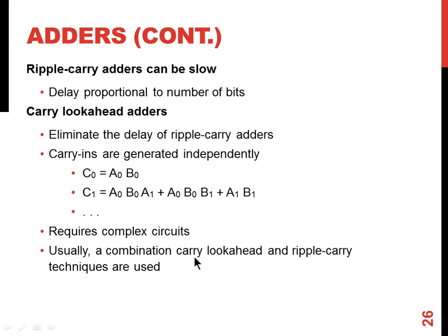For each block, you can set constraints that we can use ripple carry adder in certain cases where we don't need a high speed design, or the design is relatively lower speed. In the high speed sections of your design, you can use carry look ahead adder. So we can mix and match and get advantages of both adder circuits. Ripple carry will give me less area. Carry look ahead adder will give me faster speed but more area. You can mix and match the adder implementation for various stages of the design.